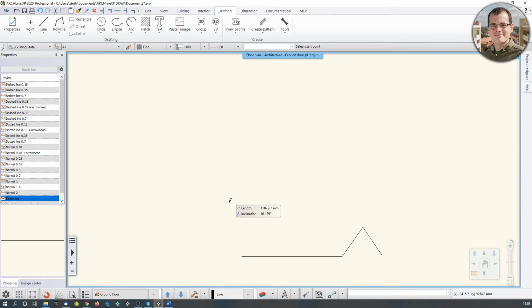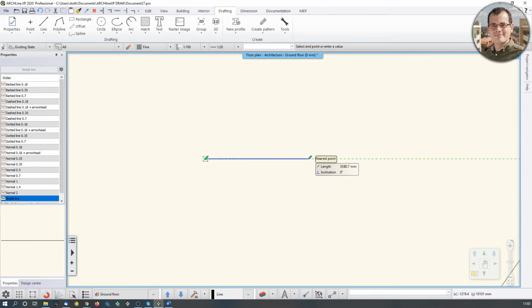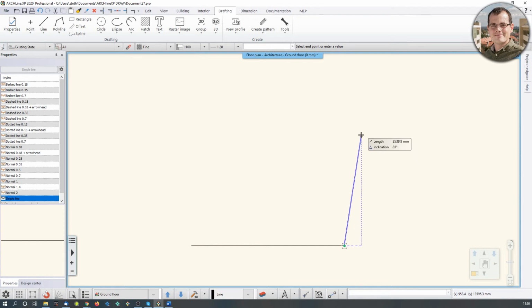Okay, let's make an exercise over here. I want to create a rectangle, which is, let's say, 5,000 millimeters in every direction. What I do is I start to pull my cursor like this, and instead of trying to find the 5,000 mark with my cursor, which is impossible, I'm just going to type in the value, 5,000. There you go. And then I move my cursor, and if I do it vertically, then the software would snap my cursor to a vertical axis, and then I can just type in the value again, 5,000.